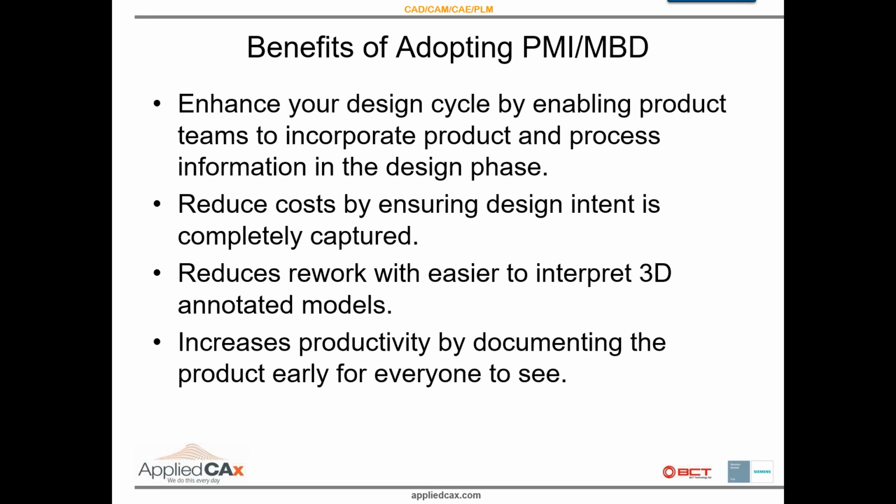So what are the benefits of adopting PMI, a model-based definition? You can enhance your design cycle by allowing people to see how the part is being put together, what the specifications are, early in the design cycle. It's not just for a single part, you can do it with an entire assembly. It allows others in the enterprise to see the designs, where it's going, and how it's going to be used.